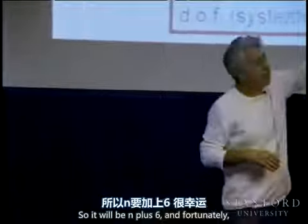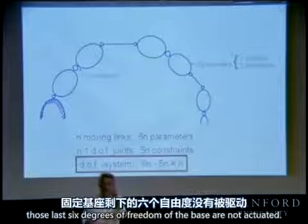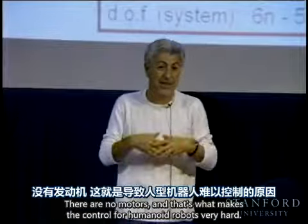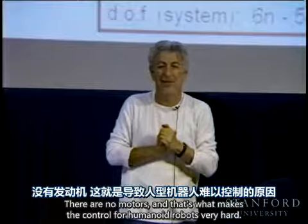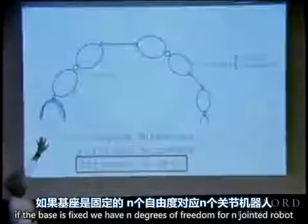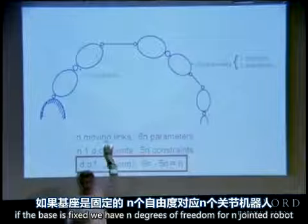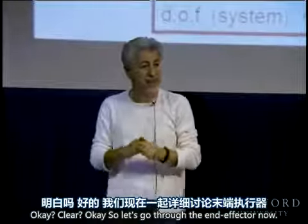So it will be n plus 6. Unfortunately, those last 6 degrees of freedom of the base are not actuated. There are no motors. And that's what makes the control of a humanoid robot very hard. However, in the case of a manipulator, if the base is fixed, we have n degrees of freedom for an n jointed robot. Okay? Clear?